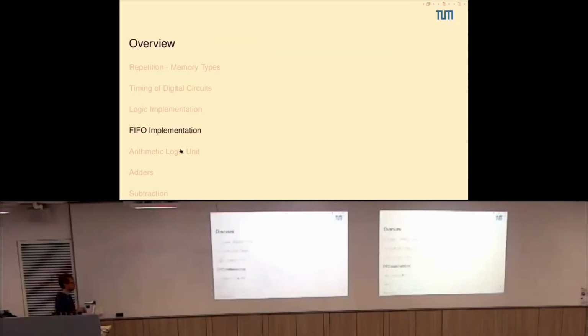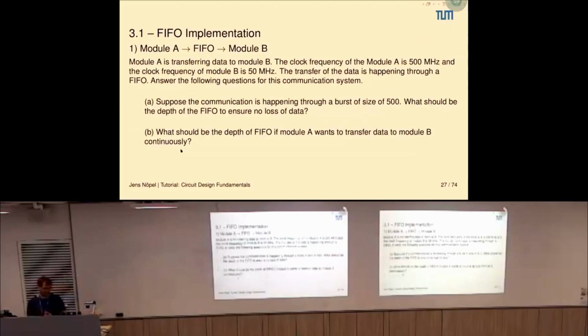Then we started already with the next topic, which are FIFO implementations. So a buffer module that outputs the input in the order it came in, so first in, first out. And usually you use FIFOs if you have 2 modules running at different frequencies.